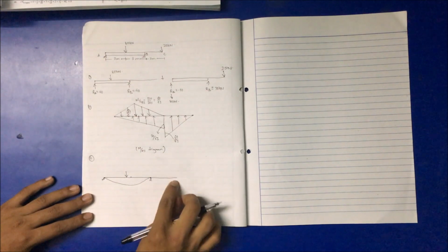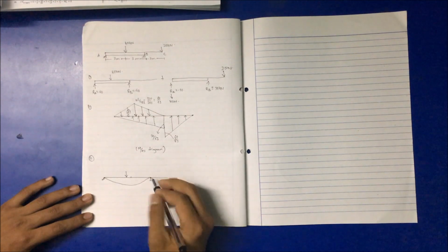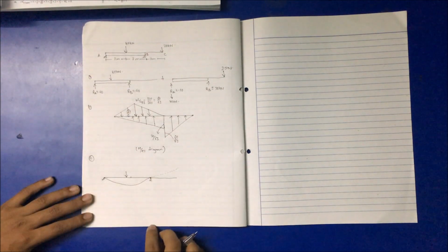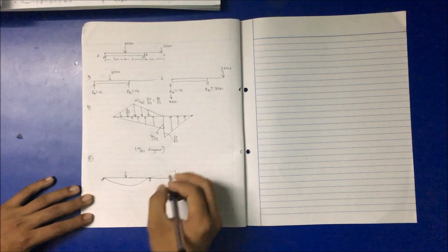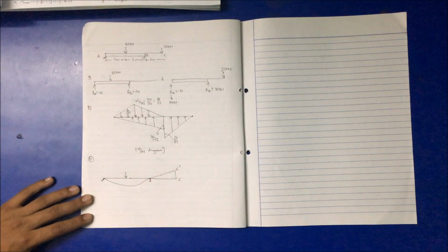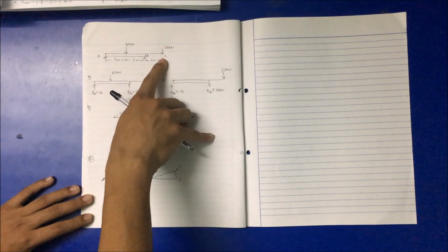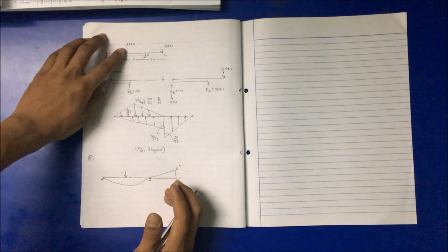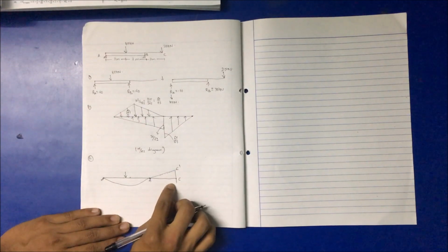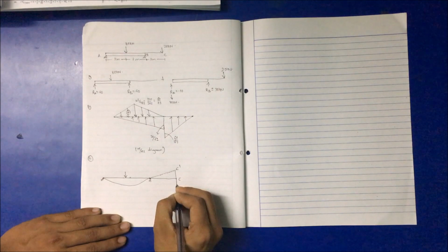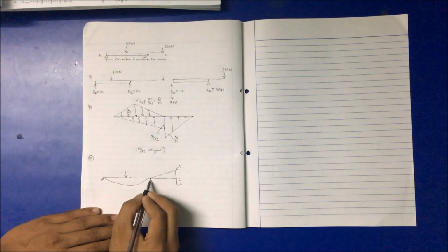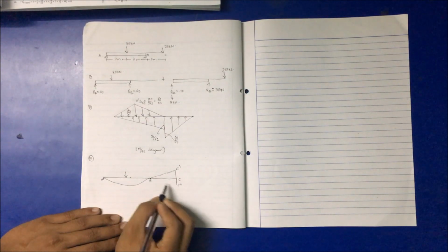And this free end being free to move, it will go upward like this. I will show you with the illustration later on. Joining this point, C dash, this part goes upward freely. Taking into account this 20 kilonewton, now not considering the 80 kilonewton, the point C will move vertically downward, and let us say this to be C double dash, but this point B being fixed,